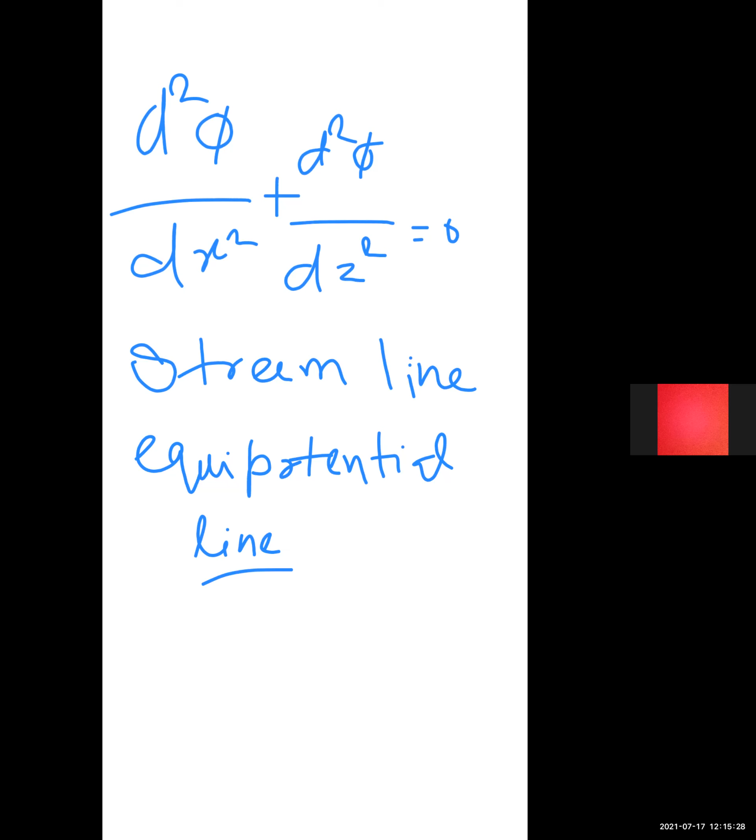At every intermediate point in its path, there is a certain residual head H that is still to dissipate in the remaining length to be traversed to the downstream. This is applicable to every streamline, and hence there will be points on different streamlines having the same value of residual head. If such points are joined together, the curve obtained is called an equipotential line.